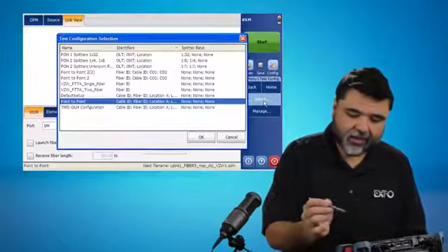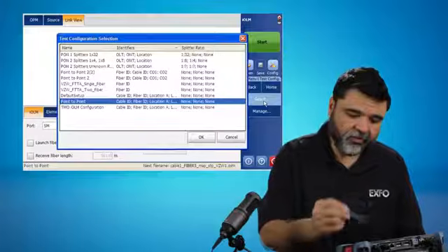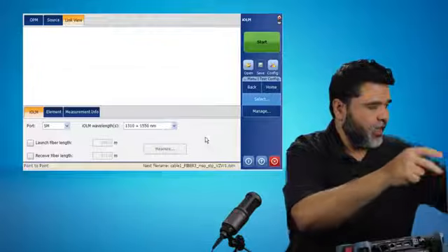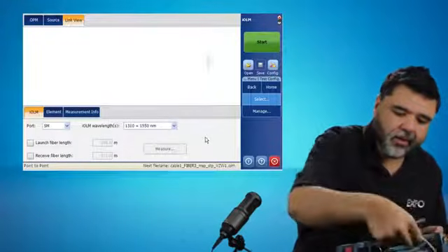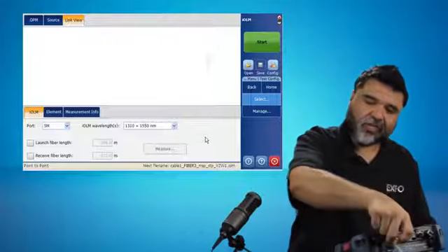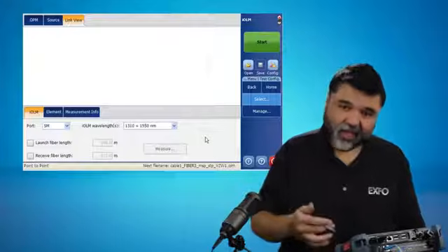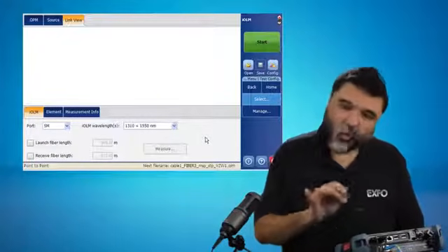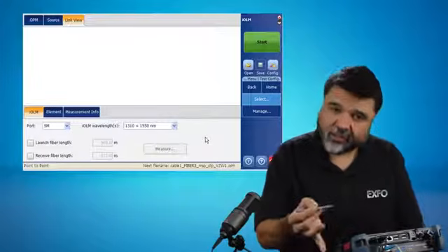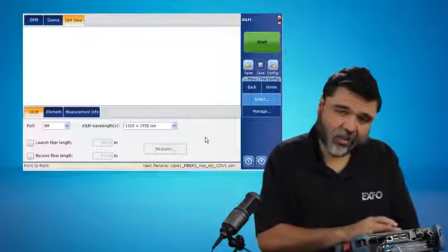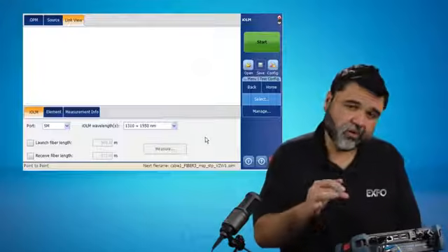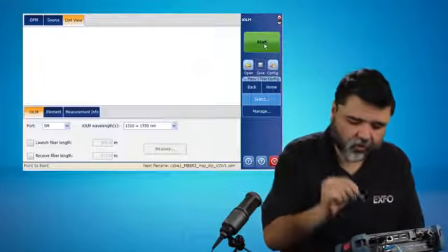So I'm going to go ahead and select the type of test I'm doing, and this is going to be point-to-point, so I'll go ahead and hit OK. I'm going to go ahead and normal this back up to the way I had it before. So I'm going to plug this back in here, and then plug this back into the OTDR. So I know I didn't clean the connector, but for the sake of time, I'm just going to go ahead and normal it back up. That's a luxury I have working for the manufacturer. And so once I've selected my configuration file, I will select my wavelengths, 1310, 1550. In this case, if I have any launch cables to null out, I can do that at this time as well. And once that's done, there's no distance, there's no time, there's no resolutions. I just go ahead and hit start.